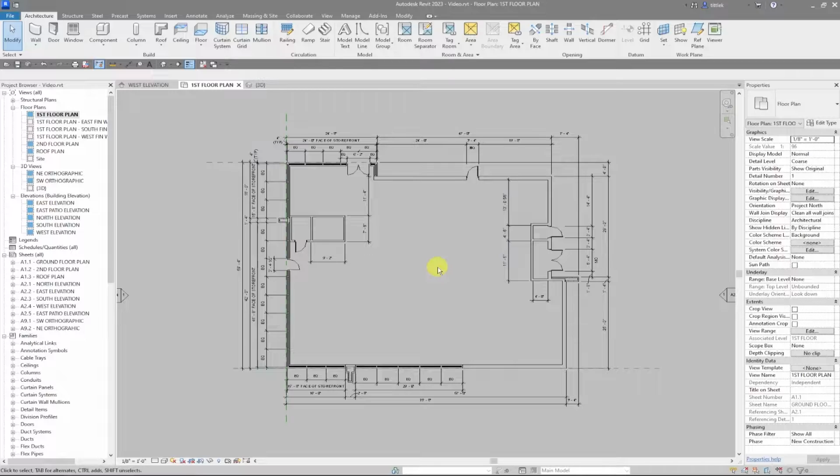The next thing that I'm going to do is start setting myself up to create 7 different exterior wall types. They're all going to be based upon our current exterior wall, so they are all going to have essentially the same structure. They're all just going to have different sweeps, which we haven't gotten into yet. So before I start developing those sweeps, I'm going to create those wall types.